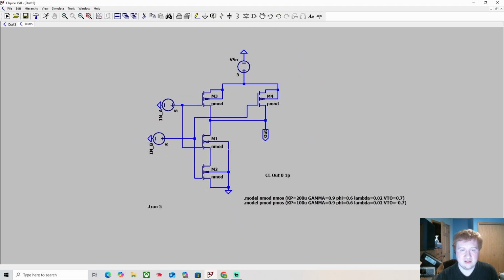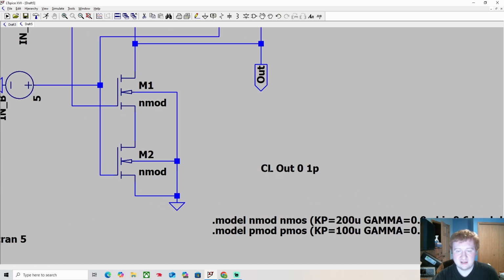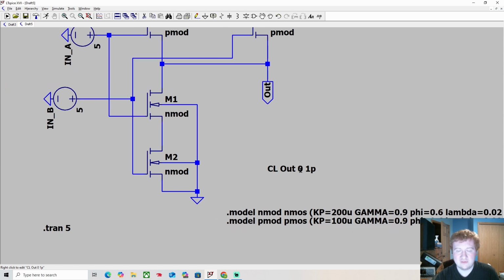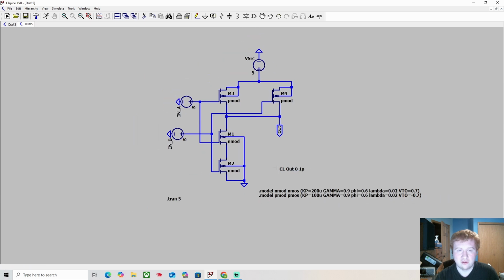So this is a model of a NAND gate. In my next video, I'll probably show how to make this into a sub-circuit using the other methods. So I hope this kind of made sense. I know that these numbers are confusing. You don't even really need this. All this does is add a capacitance and inductance to the output. Sometimes this helps make things run a little bit faster if it's getting complex. I guess I don't really need it, but I just like to throw it in there once things start getting a little bit more complex.